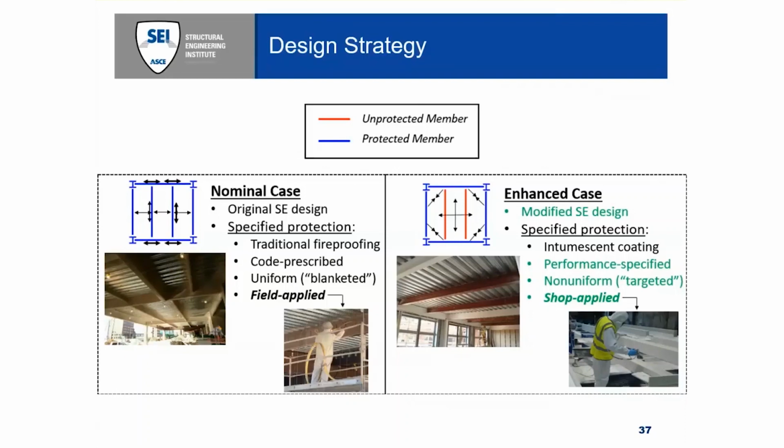We conducted our structural analysis to facilitate the safe deflection of floors, because floors, even in a furnace test, are inevitably going to undergo a large deflection. So we want to make sure that as it deflects inevitably, it's going to be safe and stable. And as you'll notice on the right side, we're not protecting all the members.